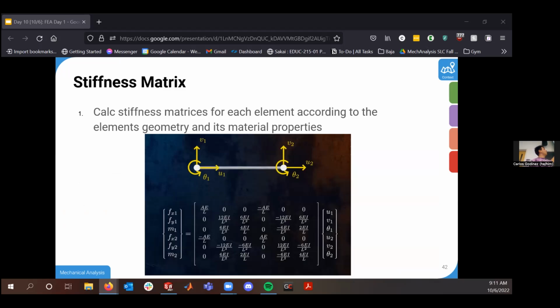What the actual stiffness matrix looks like in real life is going to be dependent on material properties. We're not going to spend time discussing every single one of these, but for example, force in the axial direction, your stiffness of how much it's resisting moving, depends on the cross-sectional area times Young's modulus divided by the length of your element. There are equations that link each one of these motions to each one of these displacements, to whatever degrees of freedom you're acting upon.